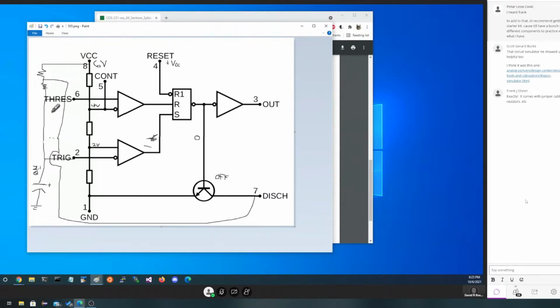Now this whole time, the other guy has been also comparing that same value. And he's not really going to act on anything until we get to 4 volts. So this rises to 3, this rises to 4. It can't be exactly 4, so we'll say 4.1 volts. This guy, 2 minus 4.1, still negative, so he's not pushing the button.